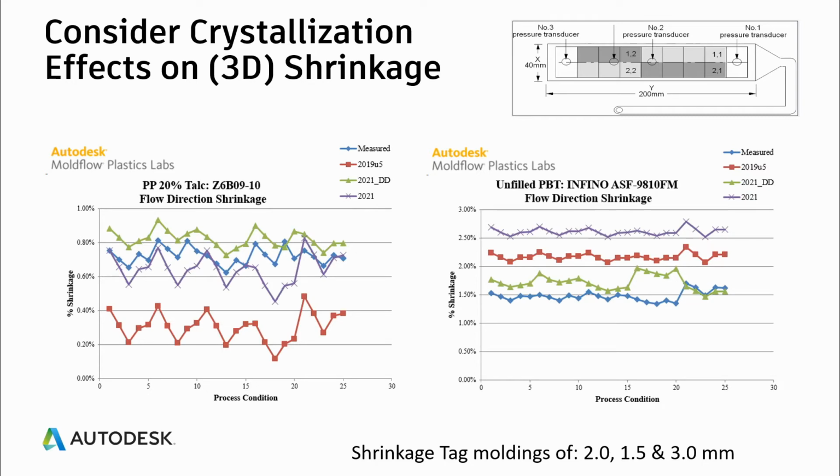Neither of these materials has strong anisotropy effects because they're not reinforced by any fiber filler. So the predictions and the measured values in the transverse direction are quite similar to the ones that I've shown here in the flow direction. So I'm not showing those transverse comparisons to you today.